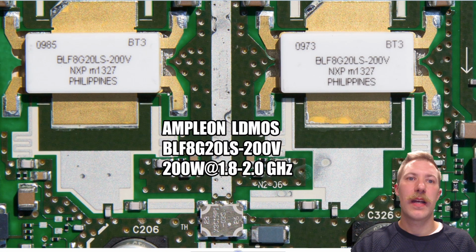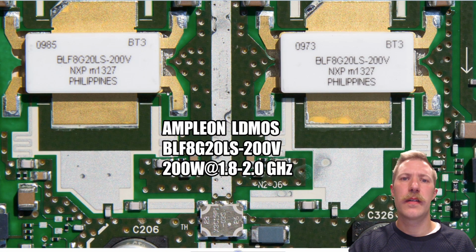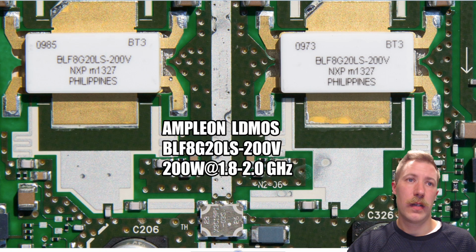are Ampleon LDMOS. Another point he mentioned due to the temperature gauge is that LDMOS is really temperature dependent when you have to control their gain, so that is most likely to adjust the input according to the temperature of the module.